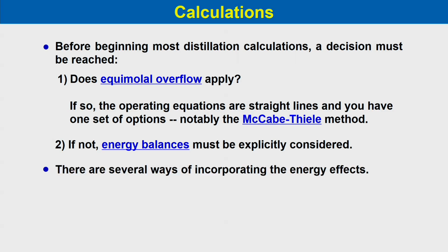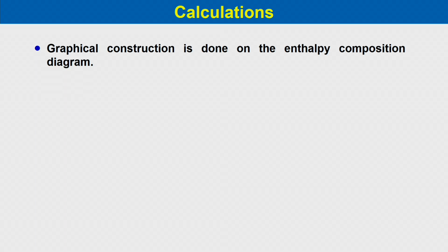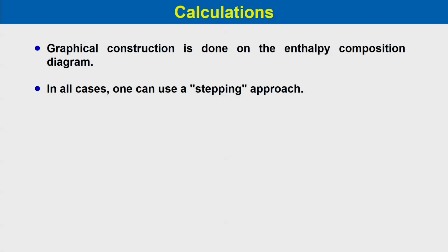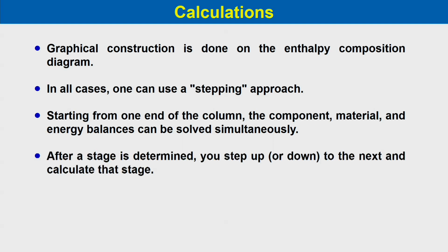There are several ways of incorporating the energy effects. One such method is the Ponchon-Savarit method, which is a graphical method that does not require an assumption of equimolal overflow. The graphical construction is done on the enthalpy composition diagram. In all cases, one can use a stepping approach. Starting from one end of the column, the component, material and energy balances can be solved simultaneously.